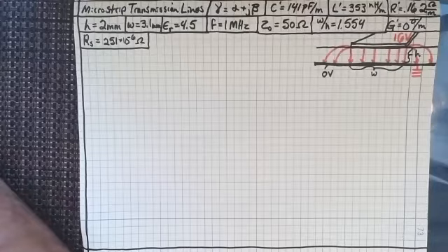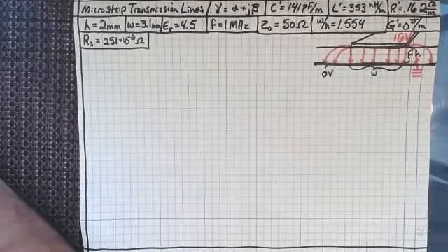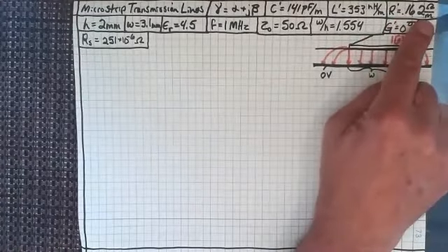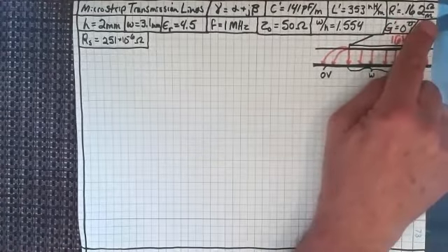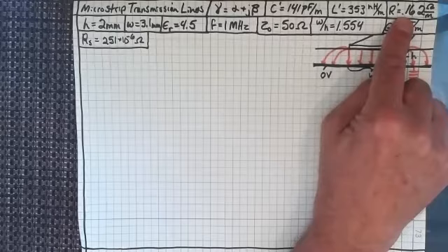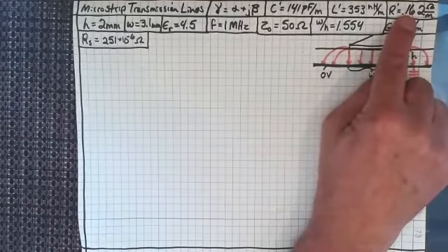Now, in a cell phone, we don't have the low frequencies. We actually have pretty high frequencies, but we do have those short distances, and that's why we can really say that we could discount R prime. Even though R prime seems relatively large, 0.162 ohms per meter, think if you went 1,000 meters. That would be 162 ohms. That would be a huge decibel attenuation, wouldn't it?